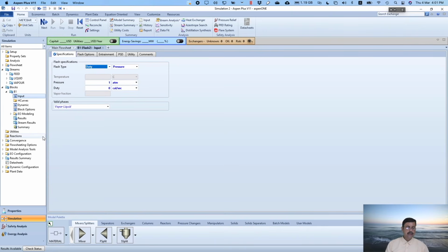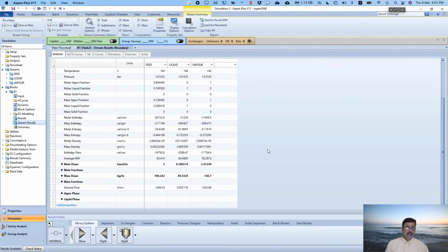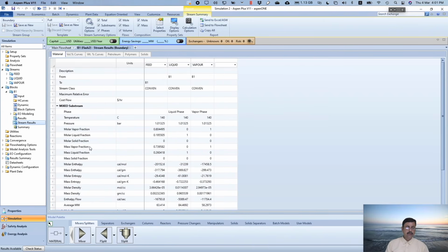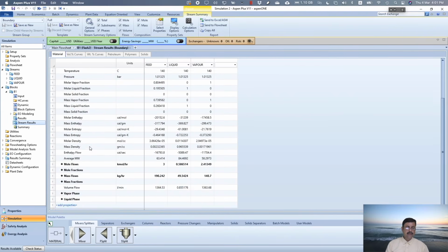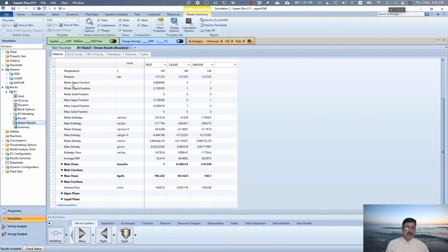Yes, now the results are available. So go to stream result. And here you will find this information. So what are the stream result information we have? We have temperature, pressure, molar vapor fraction, molar liquid fraction, solid vapor fractions, enthalpy, entropy, density, and so on.